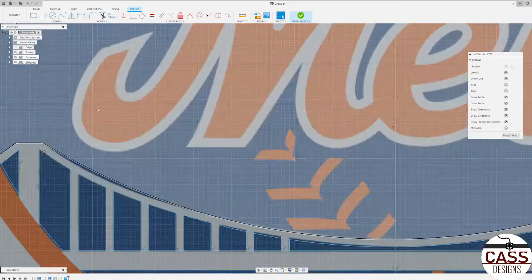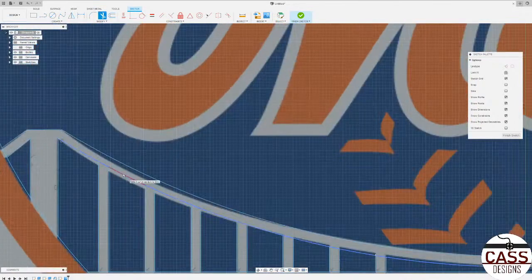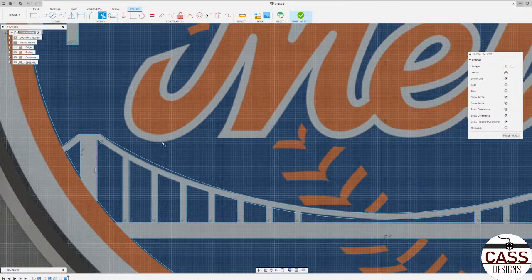And then now down here, the other modification we need to make to the sketch is clicking trim. So what this does is it trims a section of the sketch between 2 points. So right here, you can see this curve that we have between these 2 lines. We don't really want it there because we want this to be like a solid extrusion, kind of like the bridge is for the actual picture. So we're going to get rid of this. And everything you click just disappears.